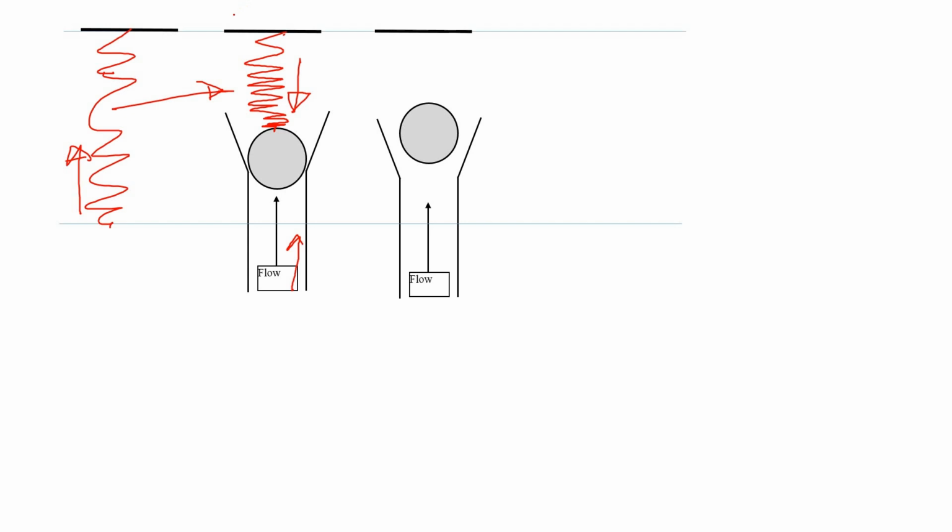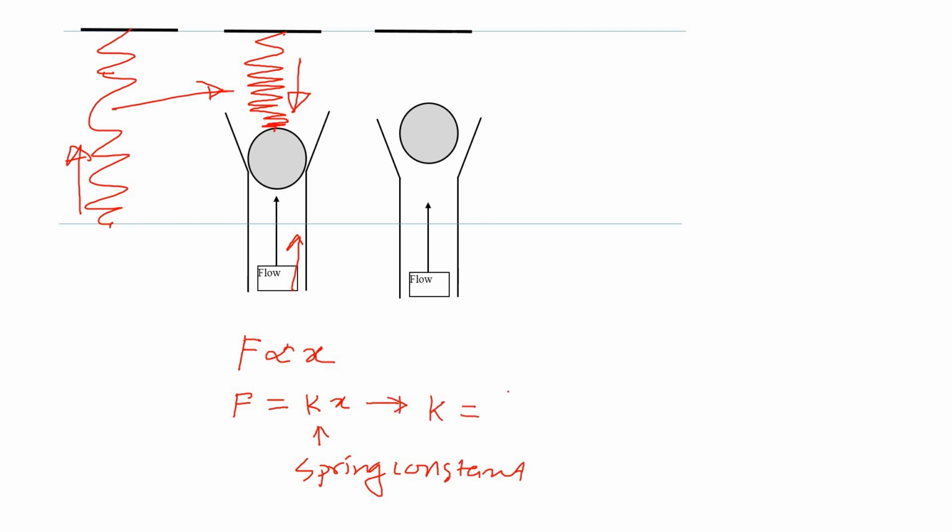You know Hooke's law, Hooke found out that the force is proportional to the compression of the spring. Now, if you take out that proportional sign, you get a constant that is called a spring constant. So this piece is a spring constant. Now, if you try to find the unit of that spring constant, you can solve for K, which then becomes F by X. So you can say in the US system, it's going to be pound per inch.